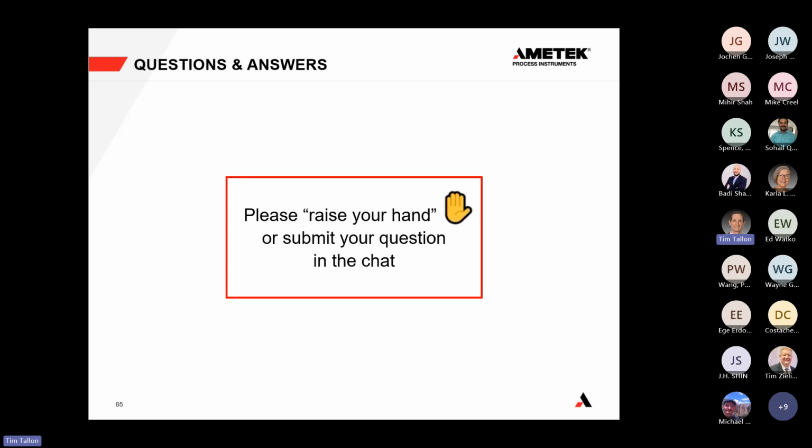I would think from a control logic standpoint, you at least need the visibility to monitor for high combustibles and very high combustibles. Those two additional interlocks, and then at least to provide those alerts to the operator. As far as shutdown, that's more of a plant-related decision, but it's important to at least have that visibility for measurement.